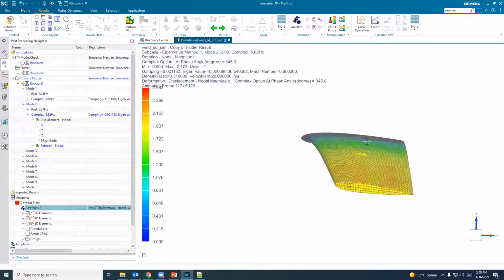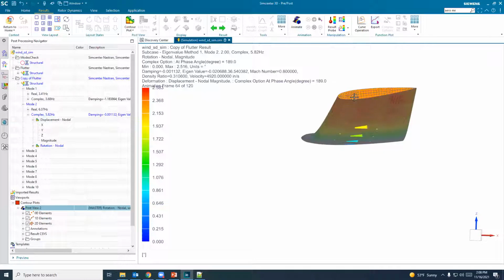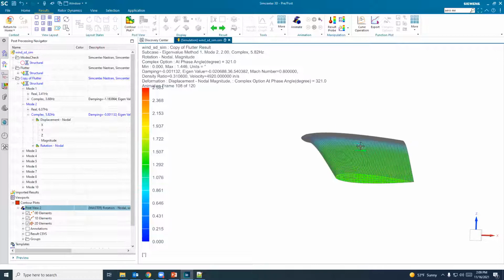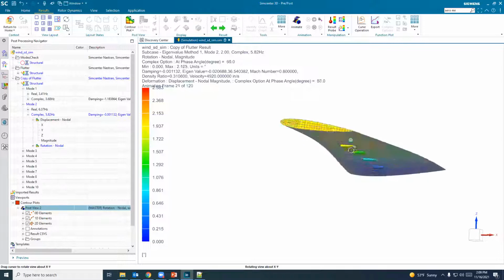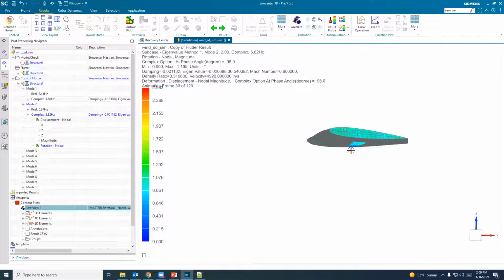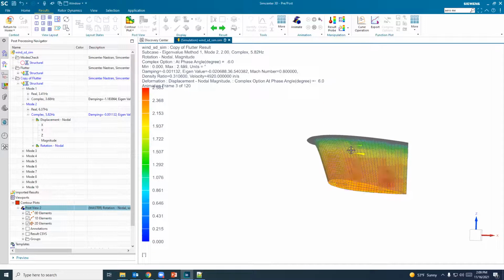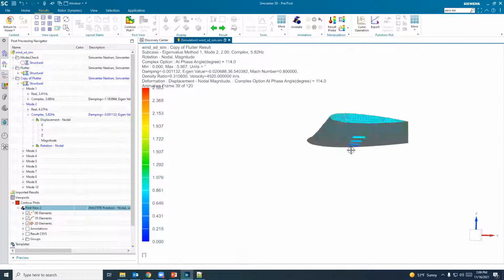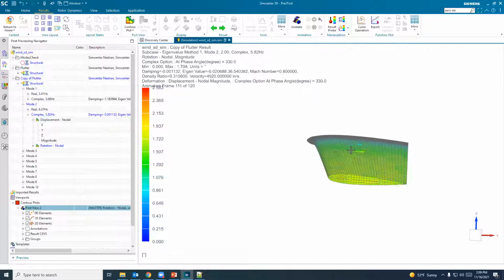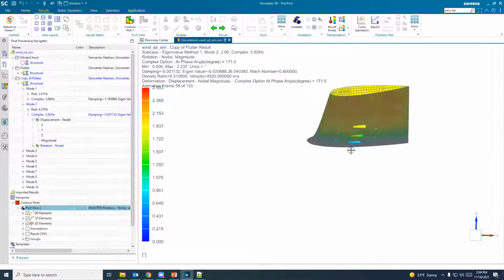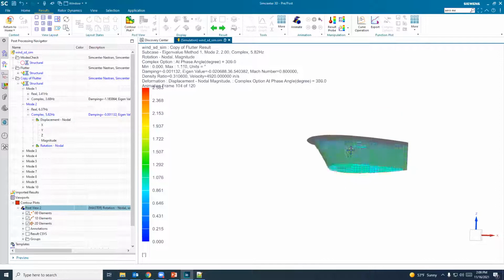we do find that for this type of result we're getting pitch up as the velocity is going up, and pitch down as the velocity is going down. This is consistent with aerodynamic force, if that's what's happening, which we found since we're at a neutral stability point here, that the aerodynamic forces are doing work on our structure, or at least enough work that they're equal. They're at the point that they're overcoming the dissipative forces within the structure. And if we proceed past this velocity, it's going to get to a point where this mode will become unstable.